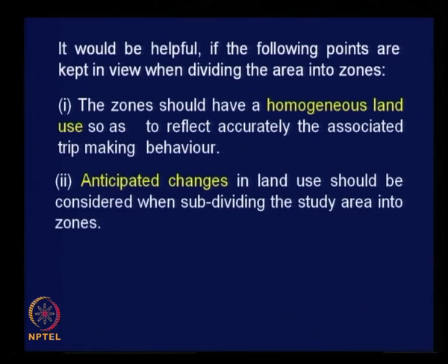Second, anticipated changes in land use should be considered when subdividing the study area into zones. Let us say one residential area in the base year is changing very fast into a commercial area, right, and it is partly commercial and there are few residential apartments still in that area. Definitely you can include those residential pockets also in this zone, so that in the near future it is going to be only a commercial land use.